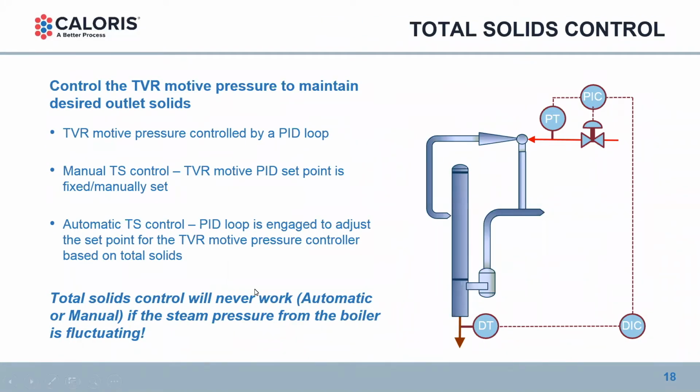I just wanted to make a note here on density control. Typically that's what we're trying to do on these evaporators: concentrate a product to a final discharge concentration. So how do you control that? Well, when direct steam heated, you put steam into the shell until you measure the discharge concentration, and you back off on the steam coming in if you're over concentrating, and then you increase the steam if you need to increase the concentration. And you control direct to the steam control valve going into the shell.